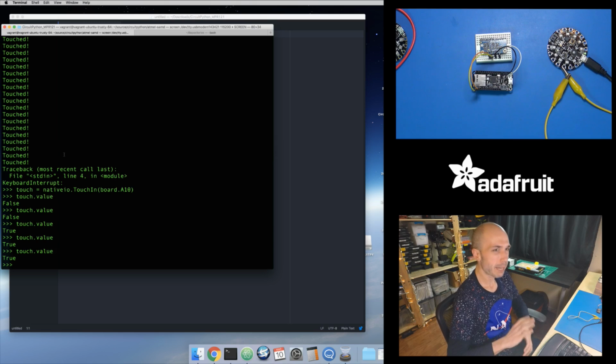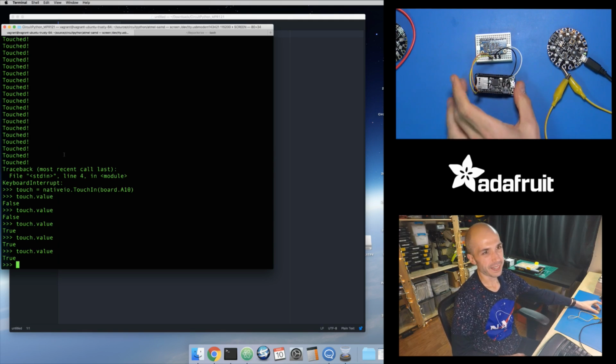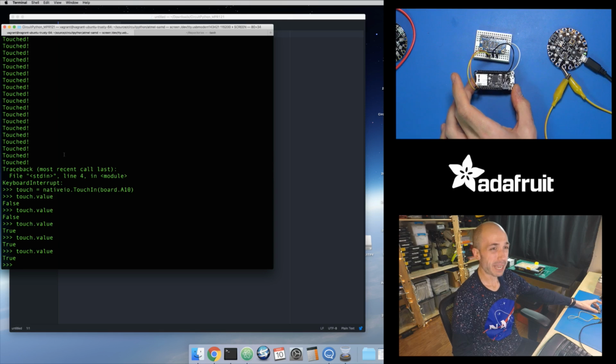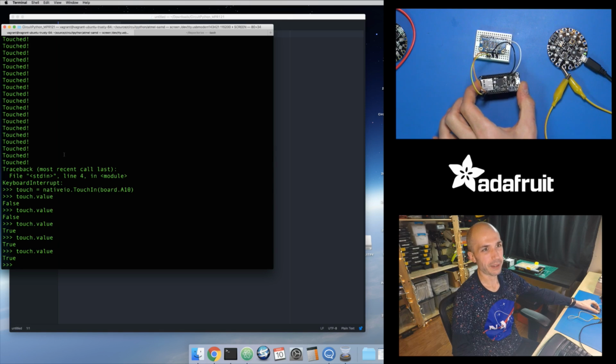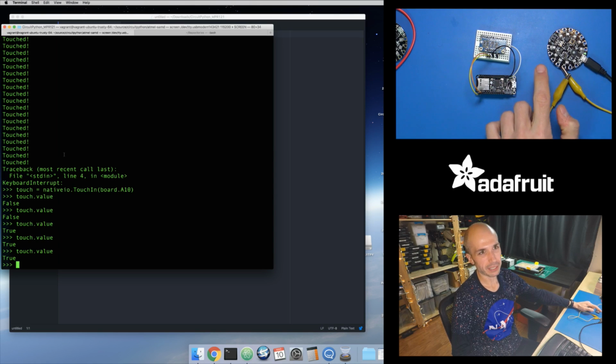And actually, maybe in the future that might change. I think Lady Ada did some cool videos where she was reverse engineering how that Q-Touch works, because right now we have to include this really large binary blob to get that support, and at the end of the day it's just tweaking some little registers, so that shouldn't require like 8 kilobytes of included source files. So maybe this will work in the future without all this giant extra support, and maybe you'll be able to use that touch input natively on these SAMD21 boards.